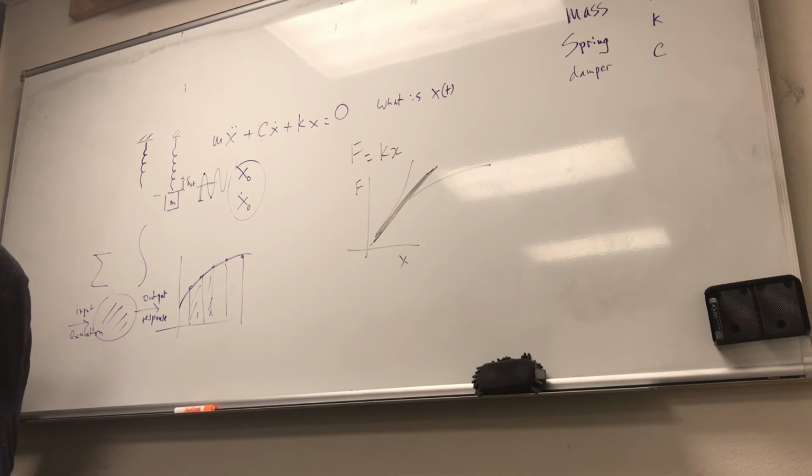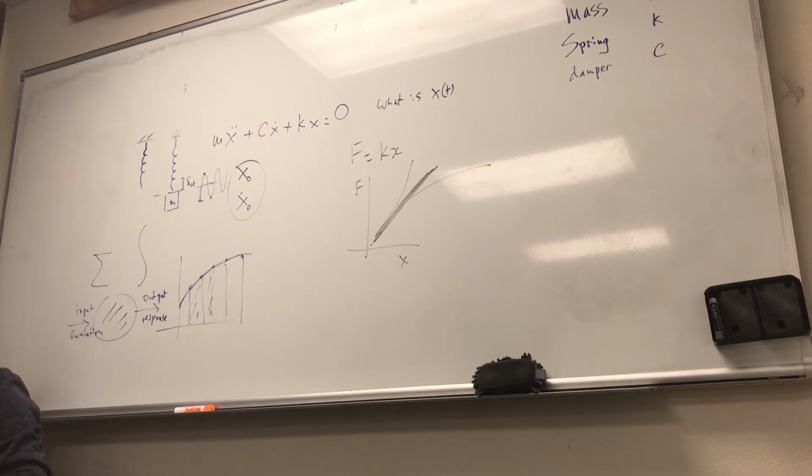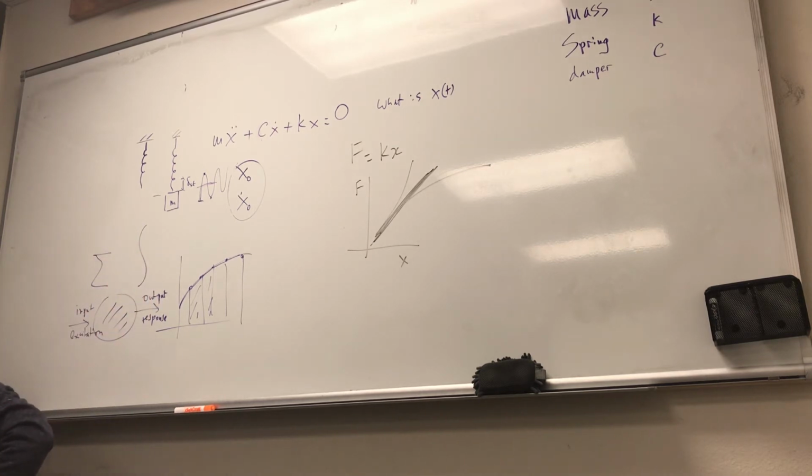A bar that is just a prismatic bar that has a weight at the end of it is also a spring, you know. A simple beam with a load in the middle that you push and then you let the beam do this can be modeled like that, as we will see. So most practical problems, that means you have a physical situation and you know that your vibrating system will have what? A mass, a spring, and a damper, but sometimes the spring is not very clear, it's not very apparent.